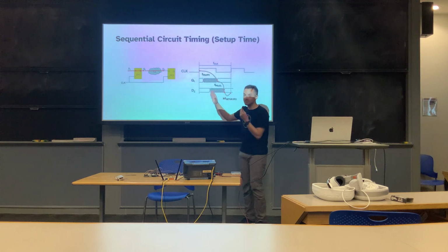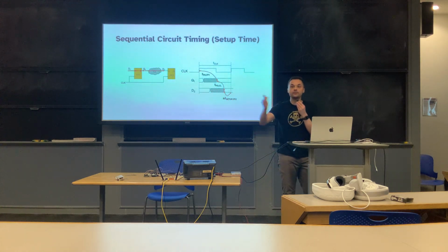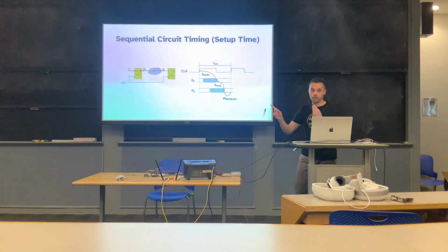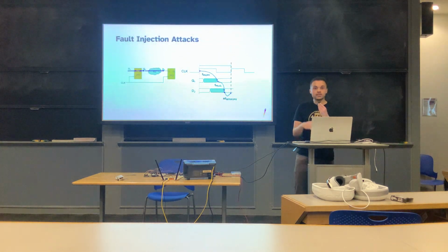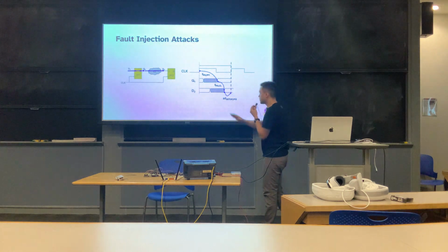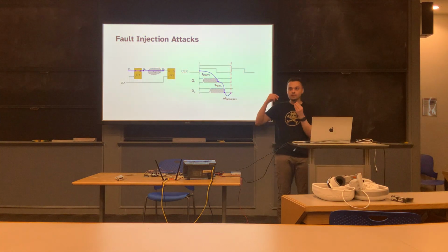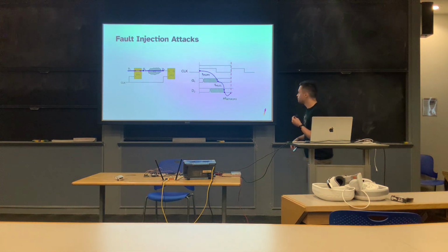So this needs to be ready not at the clock edge, but actually before the clock edge for that setup time in order for flop 2 to read the value properly. And so this will actually determine your critical path in your system. So the longest path between two flops through some combinatorial delay is going to be the limit how fast you can run your clock at.